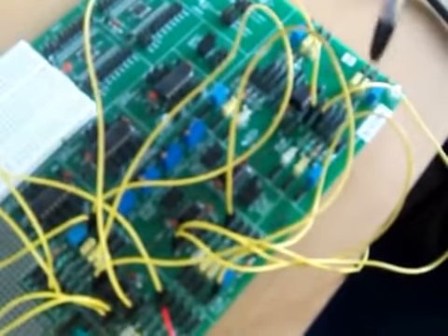What happened was, we were one resistor short. We didn't have one resistor, so instead of putting a resistor on the breadboard over here, we used this branch over here. In the sense, we were short of a 1 kilo ohm resistor, so we took a wire from the U2 P1 port, U2 P2 port, and we connected it over here. So instead of using a resistor on the breadboard, we actually used the resistor which is already given, without connecting the fourth op-amp over here.